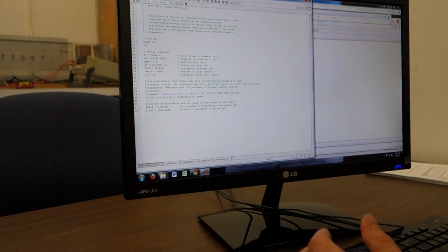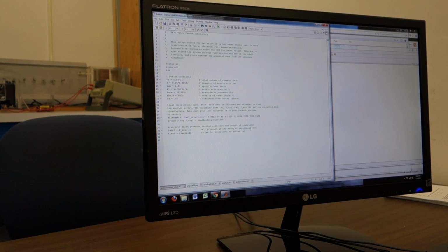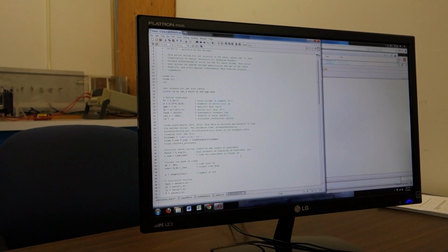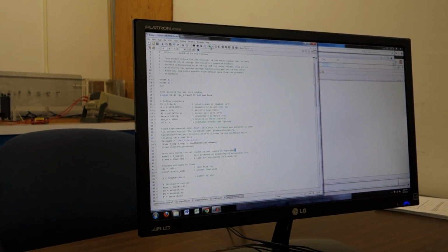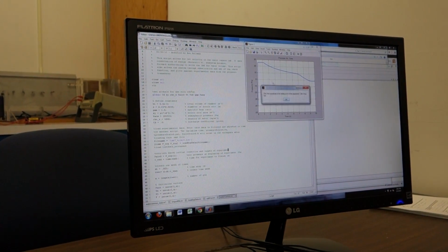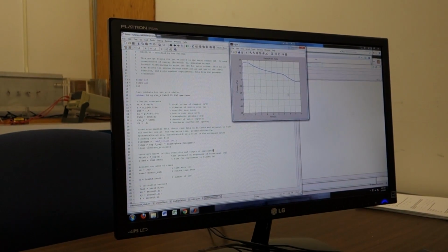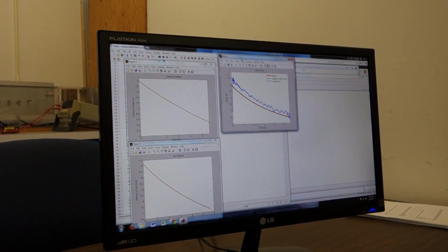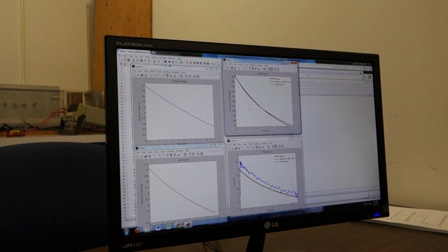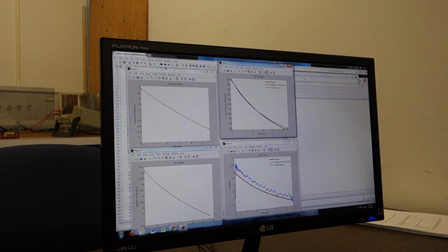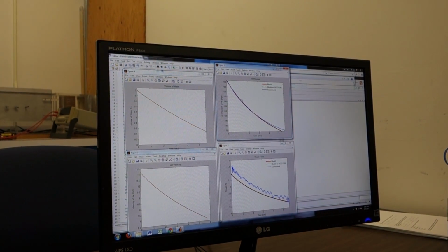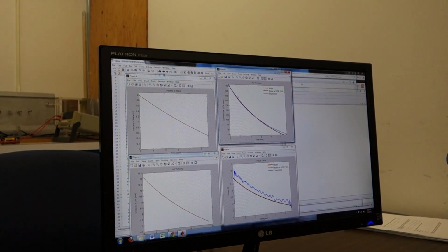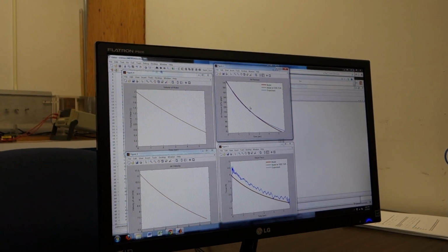So now what I'd do is continue to write my Matlab according to what's on the whiteboard, but to save time here, I'm going to go to the end. So this is a script which already exists, and will perform the same process here. And we'll see that we're plotting volume of water, jet velocity, thrust force, and air pressure. Now the air pressure looks great. The blue line is what we measured in the experimental setup, and then the red and black lines are both models, the analytical model. They all agree fantastically, which is pretty cool.